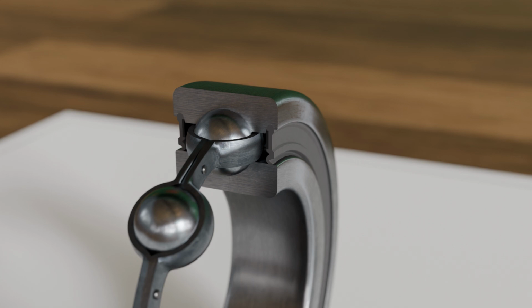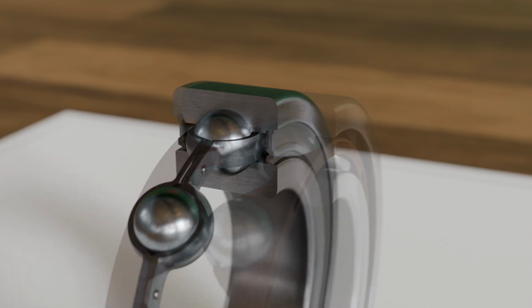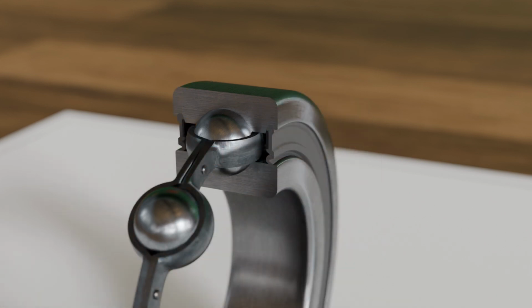If the load capacity of a single-row bearing is not sufficient, double-row designs are used. Double-row deep groove ball bearings contain 2 rows of balls within a common inner and outer ring. Compared to single-row bearings with the same inner and outer diameter, they have only a relatively small additional width but offer significantly higher load capacity. As mentioned earlier, radial deep groove ball bearings are especially designed for radial forces, but they are also suitable to a limited extent for axial forces.